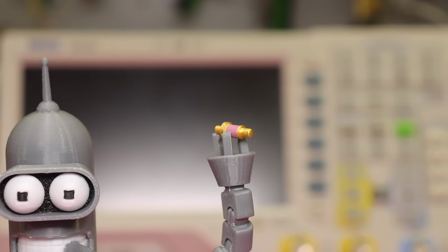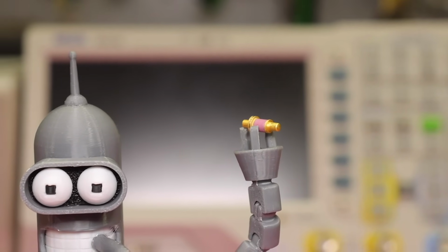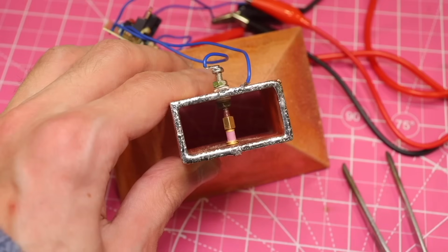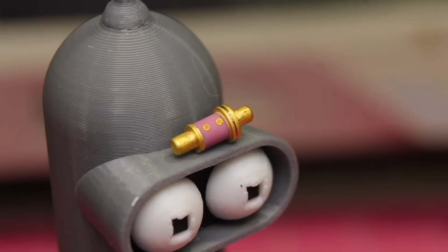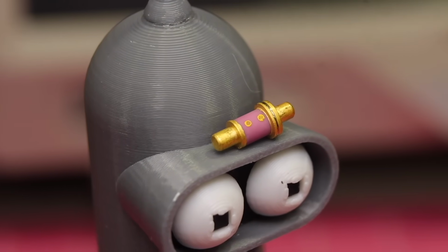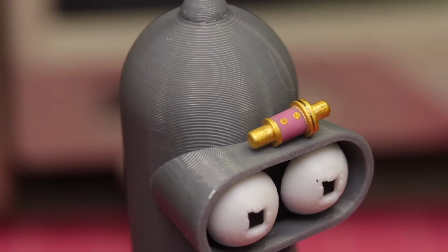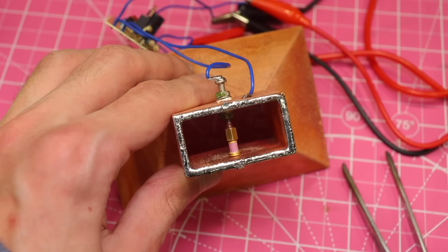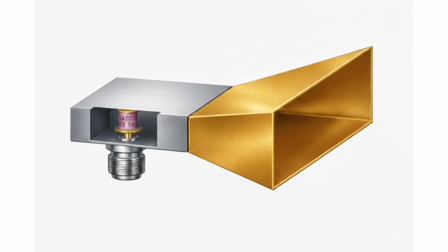The operating frequency of such a generator is determined by the electromagnetic resonance of the structure in which the diode is placed. And the physical frequency capabilities depend on the length of the diode's crystal itself. In this antenna design, the frequency is set by the distance between the diode and the rear reflecting wall. That is, by the electrical length of the resonant cavity.